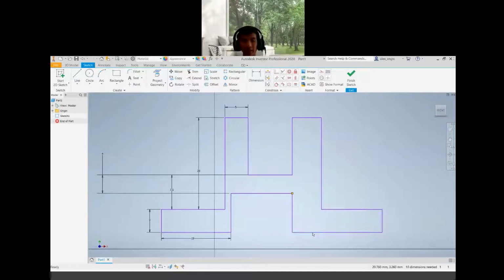So actually you can delete that particular line. Okay. You see another line because just now we created two rectangles here, right? So you have redundant lines at this part. It's best you delete the line itself because you have another line here, which is more relevant to the shorter one. Okay, you see?